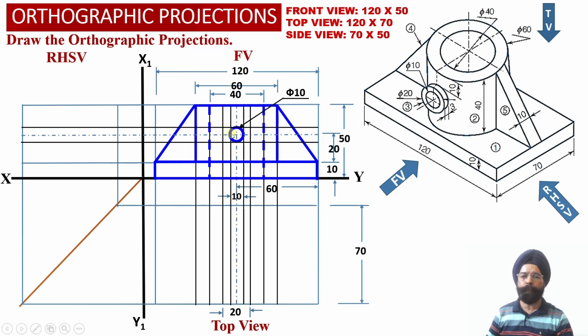And the moment we obtain this 10 millimeter circular projection as a true shape projection, now two horizontal black projector lines with an offset of 5 millimeter on either side of the center line we have to draw into the front view orthographic projections, and these two horizontal projector lines we have appropriately transferred into the right hand side view orthographic projection view over here.